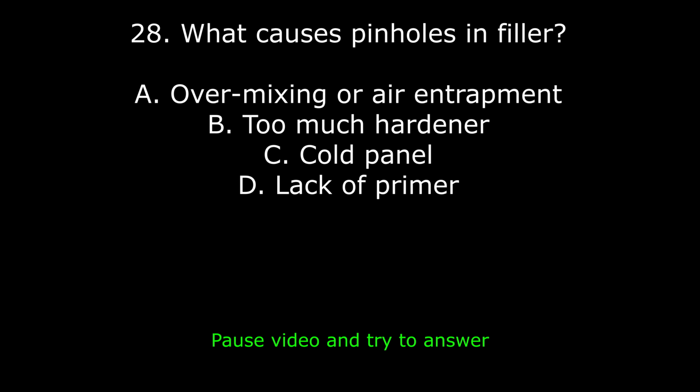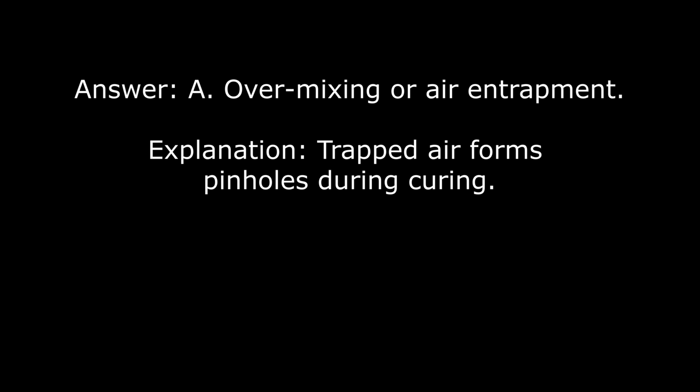28. What causes pinholes in filler? A. Overmixing or air entrapment. B. Too much hardener. C. Cold panel. D. Lack of primer. Answer: A. Overmixing or air entrapment. Explanation: trapped air forms pinholes during curing.